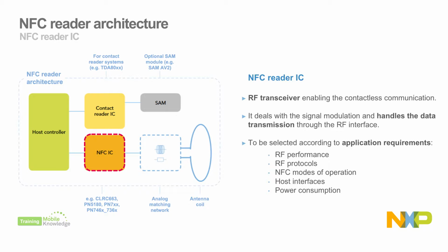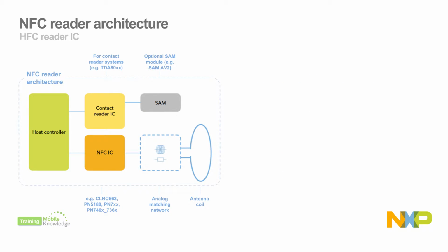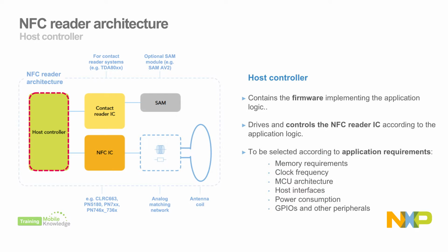We should select the appropriate NFC reader IC considering the application requirements. Among others, we need to take into consideration aspects such as the RF protocols supported, single or multi-protocol reader, the NFC operation and communication modes, the RF performance, especially for NFC Forum and EMV co-compliancy, the host interfaces, or the power requirements. The host controller contains the embedded firmware and manages the NFC reader IC according to the application logic.